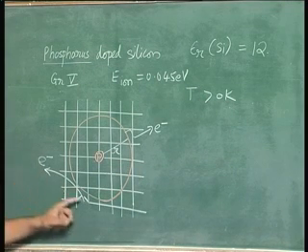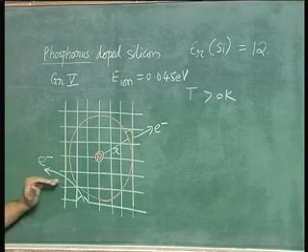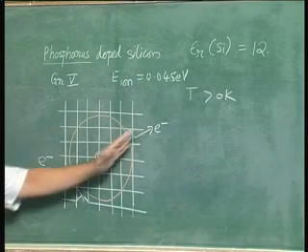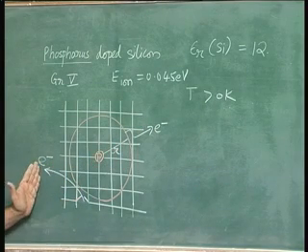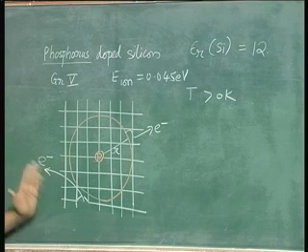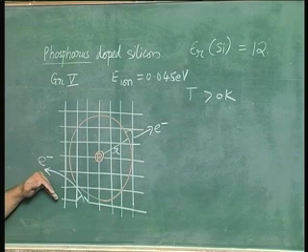So this process of electron hole pair creation is an independent process which also goes on. Like impurity ionization, which gives rise to an electron, there is also silicon ionization which gives rise to an electron hole pair. So this will be an additional source of carriers.